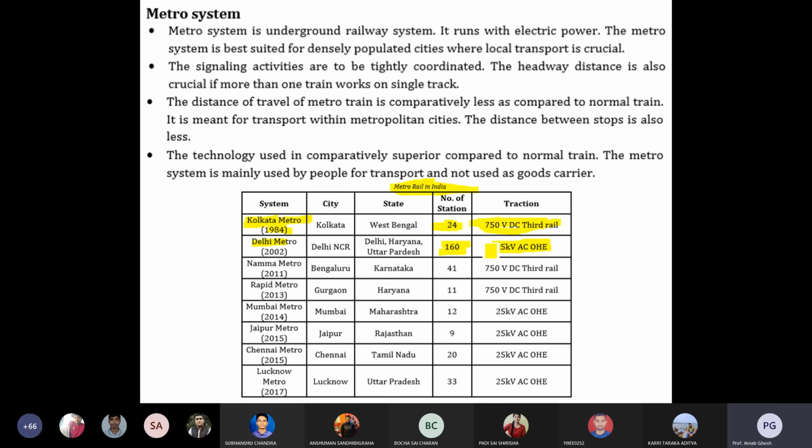Whatever we are doing, some idea is there. Why 25 kV? 25 kV means the transmission loss will be less, and directly you can collect it from the traction substation. One substation is there that is known as the traction substation. You can see the specifications for railway systems, the voltage rating specifications and other measuring instrument specifications, are quite different from normal conventional power system equipment.